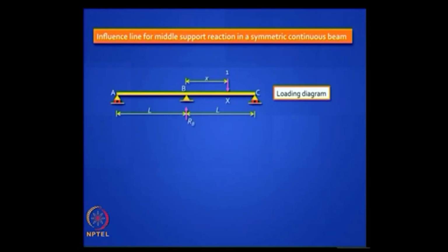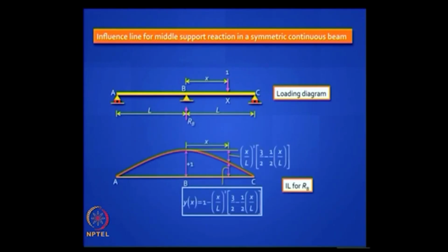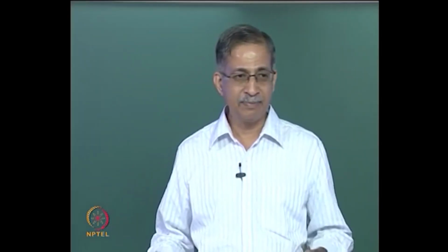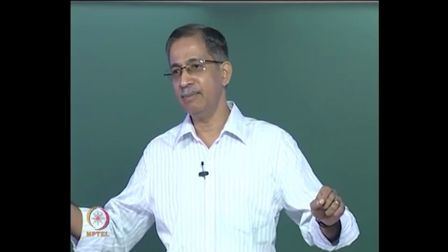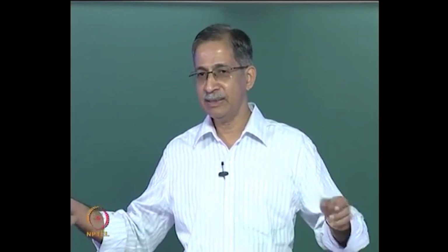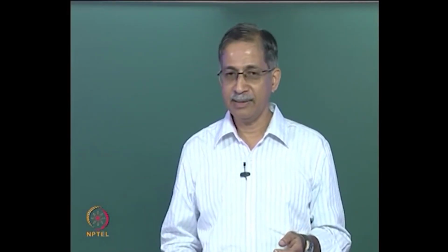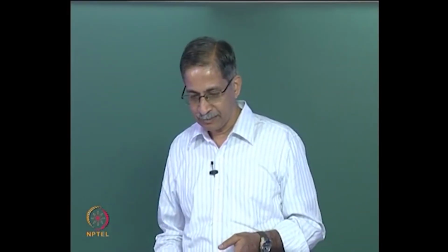Now if you want the exact equations, you have techniques of doing that, okay. The exact equation, for example, is something you can generate, and there are handbooks available where they don't give you exact equations, they are useful in bridge design, where you get the ordinates at different locations. You divide the span into about 10 segments and you get those locations, and they are sometimes used in practice.